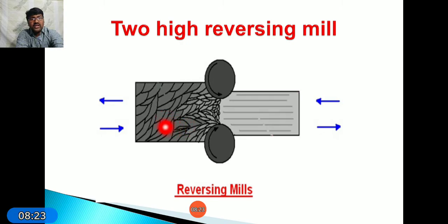Next, whenever we pass the workpiece in between the 2 rollers, what happens here? The cross section will be reduced and the grain size will be reduced. Refining of grains and forming of new grains in the material is known as recrystallization. Like that we pass the workpiece in between the 2 rollers. Again, in the same way, we send this workpiece in this direction; at that time the rolls will rotate in reverse to the indicated arrows, and like that the process can be carried out.